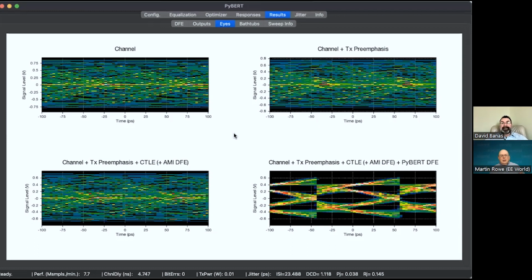You can't tell anything from that. You would be hopeless to try and recover the signal from this one over here. And that's because the high frequency content has taken what started out theoretically as an infinite speed or zero time rise or fall, and because those high frequency components have essentially been filtered out, the rising and falling edges are no longer vertical.